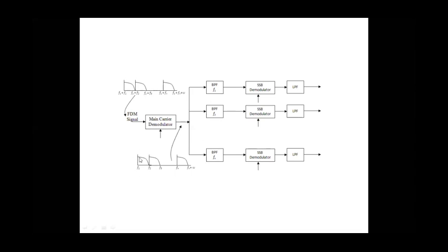First band signal is from F1 to F2. Similarly, the second one will allow only the second band. Finally, the last one will allow only the last band, isn't it? So the input to all these a set of band pass filters is same, but depending upon the frequencies to which the band pass filters are tuned, they will allow the respective bands.